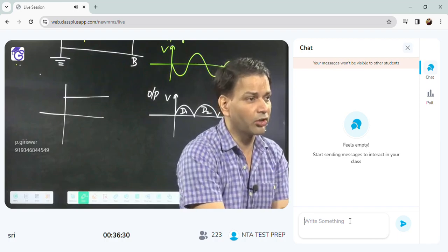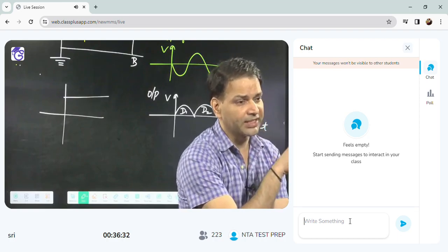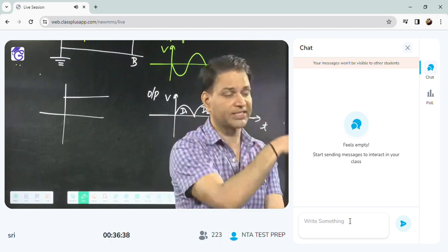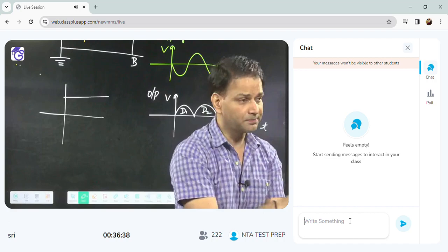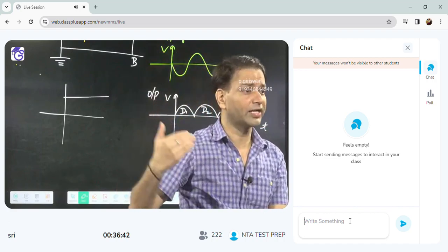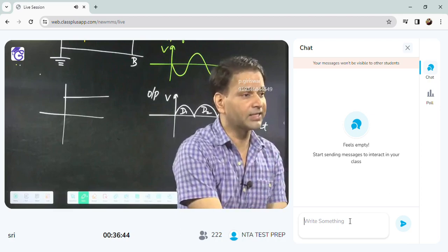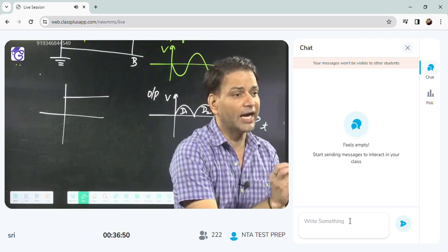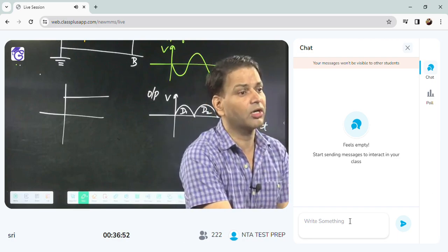This everybody got. What is the meaning of pulsating? Pulsating means here magnitudes are going up and down. Magnitude is not constant. So that is a pulsating DC. Second thing, some AC component we are also getting because in the reverse biasing, current will not be 0. Current will be small, but it will be there. That's why that AC component in the DC is called ripples.